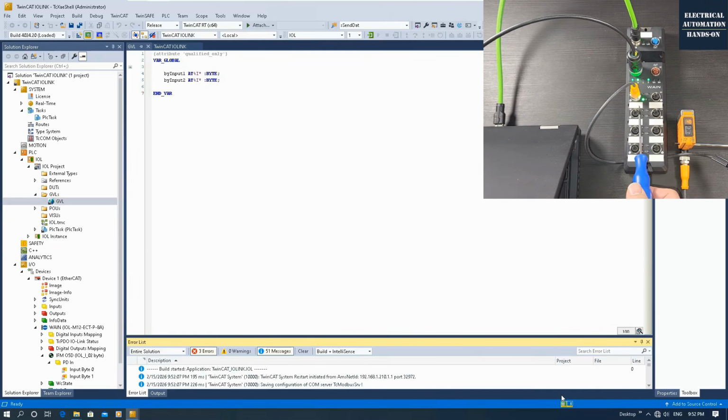Before it was gray. So that means now this IOLink master with EtherCAT function has communicated with this EtherCAT master, which is my laptop. And this one also means this master identified this device. The IOLink device is measuring this 48. So we will see it's measuring 48. Now 22, 21 now.